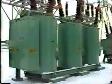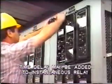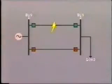The actual time will depend upon the nominal breaker voltage. In addition to this, a minimum time delay, say 5 cycles, may be added to the instantaneous relay operation. So the total time delay for reclosure may be about 35 cycles.